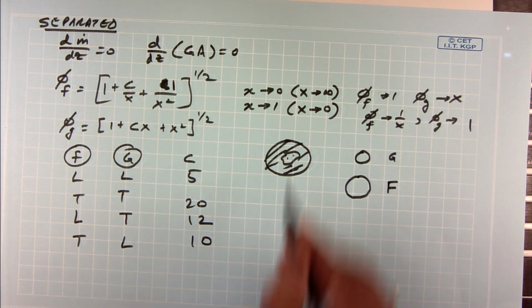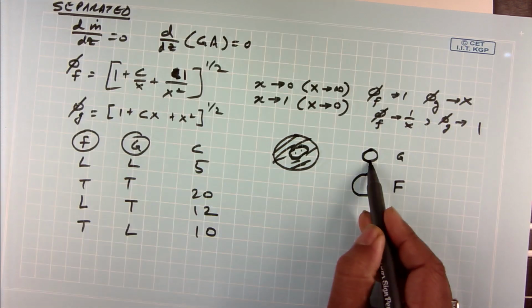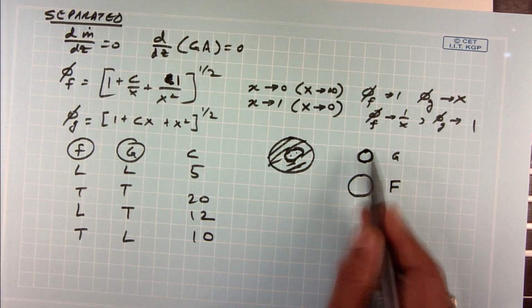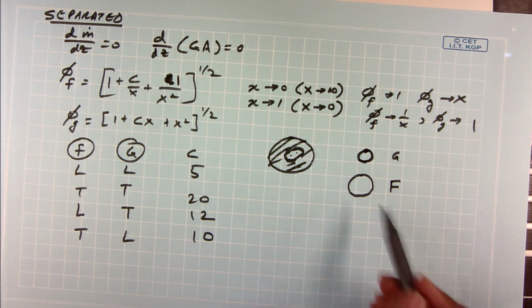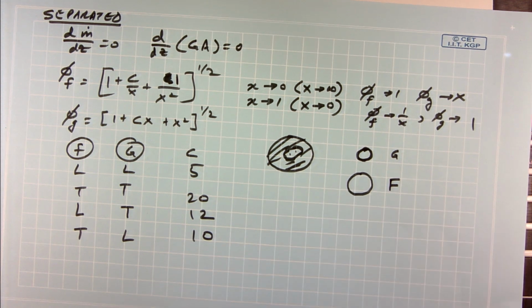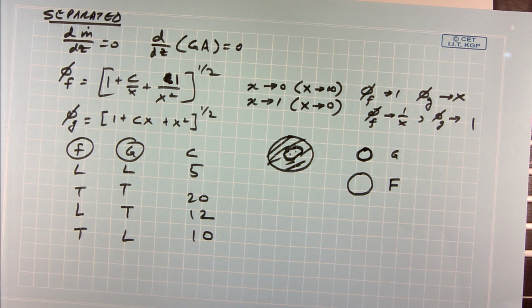So, whatever is the cross sectional area of your gas phase from the void fraction, I replace it with a tube of same area. Okay. The diameter that will correspond to that area, I can replace it with a tube, and similarly the remaining part of the total area is your liquid phase. So, I replace it with a pipe with a diameter that gives me the same area as the liquid, and then I can calculate all the flow parameters for each of these two pipes separately.